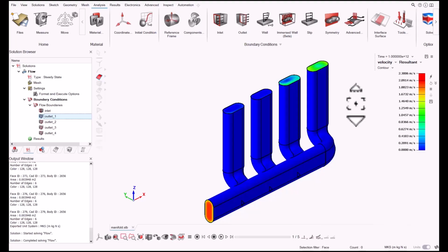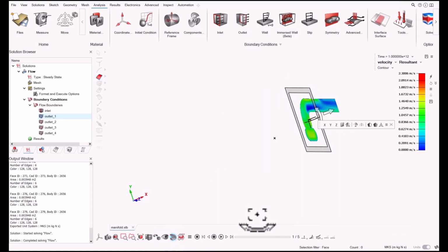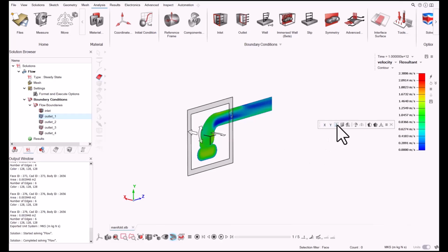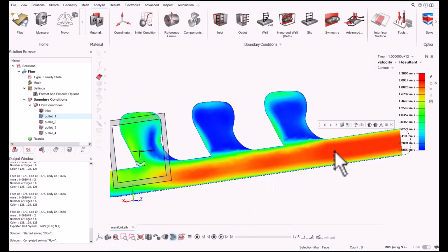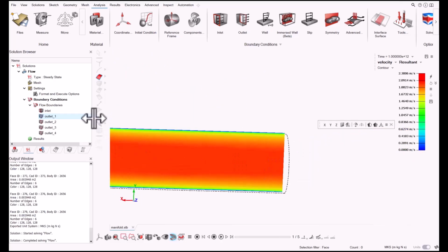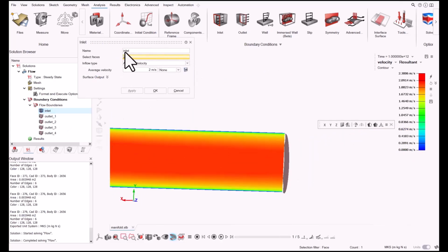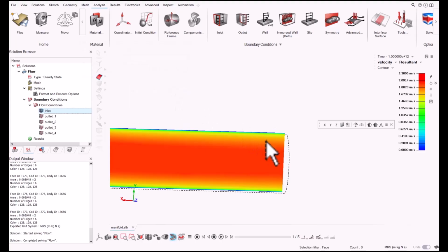In this multiphysics post-processing, I want to show you how to do certain operations to get the parameters of interest that you want. So let's start by creating a section cut in the Z normal direction. You see that because we prescribed an average velocity, which means that velocity at the inlet is going to be parabolic, you see a nice profile going in at the inlet.